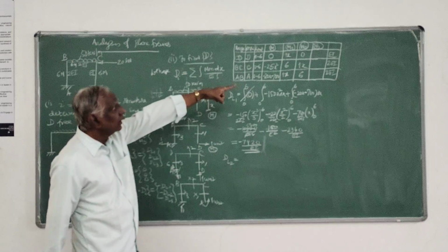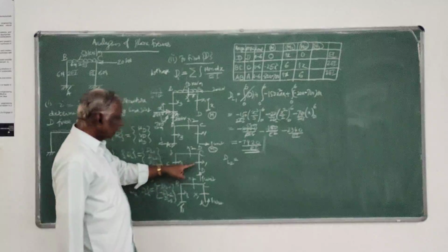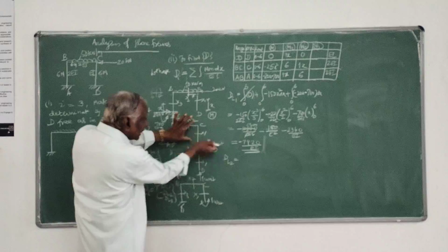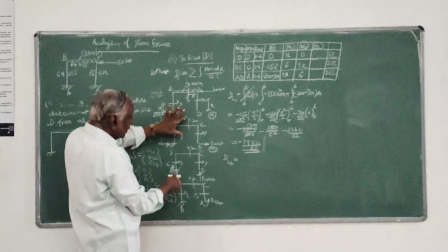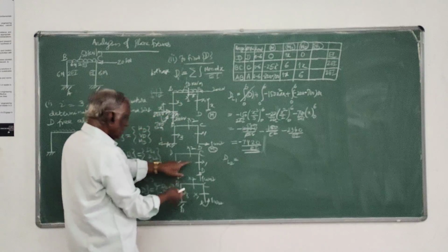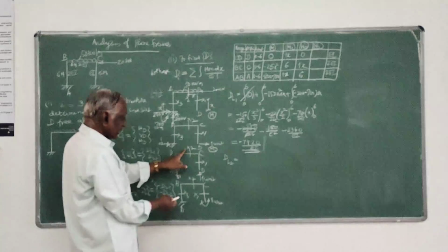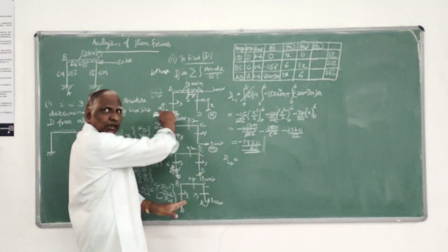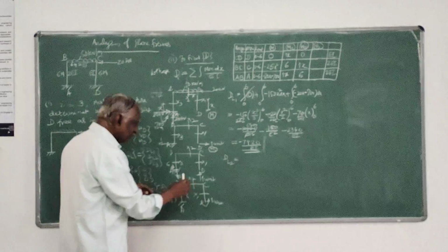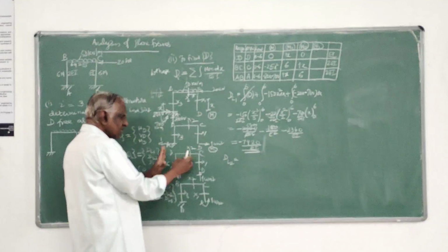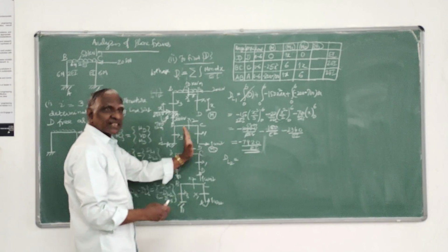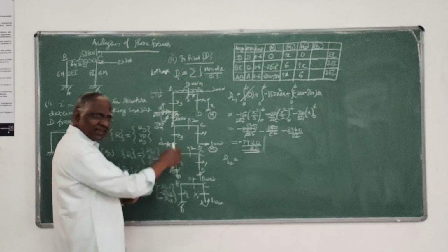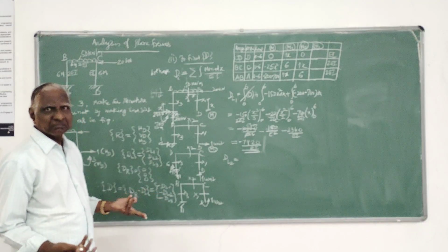AB only. But when we come to the CB span, BC, horizontal, section X2, we consider 1 unit because the 1 unit is also acting at C. You have to see the line of action of the force and the section. If it is not coinciding, I would have taken moment.